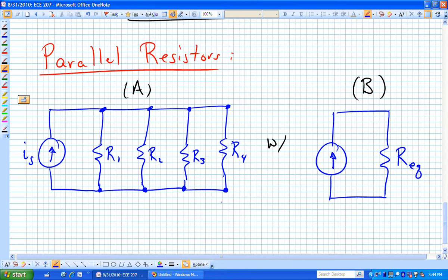Or maybe it's going to be a sinusoidal current source and it will be going up and down as a sine wave. Yes, sir? Is there a voltage drop across it? Like if we did KVL, would you just do nothing there? So the question is, what if we tried to do KVL with a current source? We don't know what that voltage is going to be, do we? Because it's going to be whatever it needs to be in order to satisfy the specification of that source.